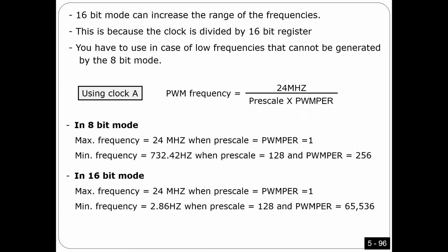So the last thing I want to say: this is 8-bit mode. 8-bit mode means no concatenation. If you concatenate, I'm going to call it 16-bit mode. And they call it 16-bit because the period is going to be 16-bit. Because I'm going to get the period from here, the period from here, I'm going to have 16-bit. Look at the beauty here.